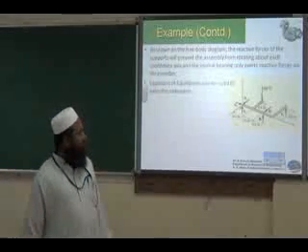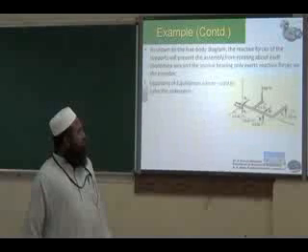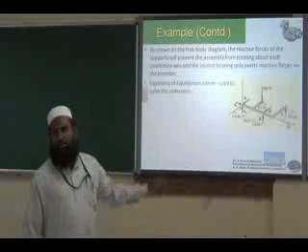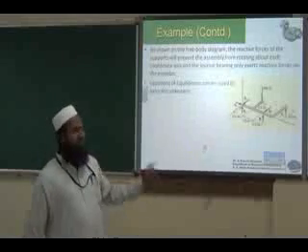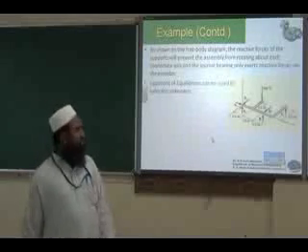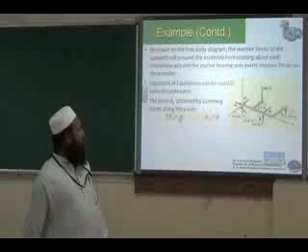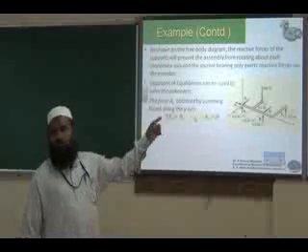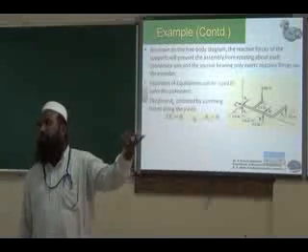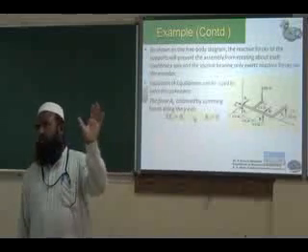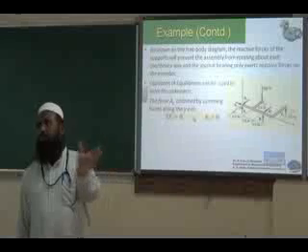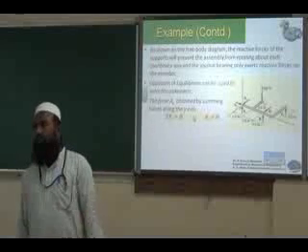So consider all the forces now. You have only one force existing in y direction. There is no other force in y direction. So if you write sigma Fy equal to 0, since there is no other force in y direction, your Ay will be equal to 0. In order to make the system equilibrium, your sigma Fy should be equal to 0. So Ay will be automatically 0.